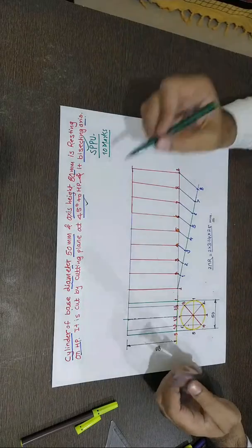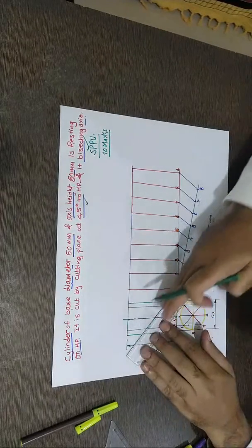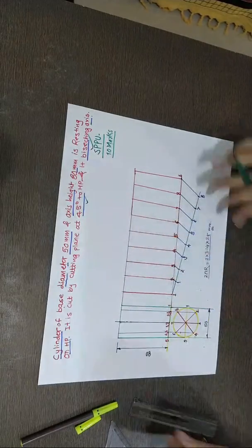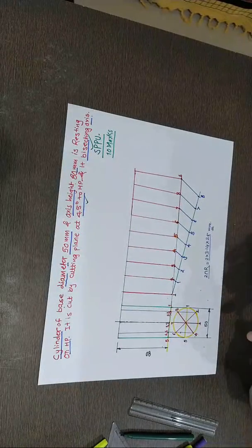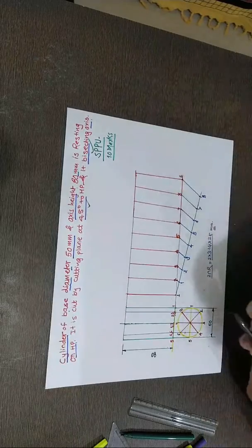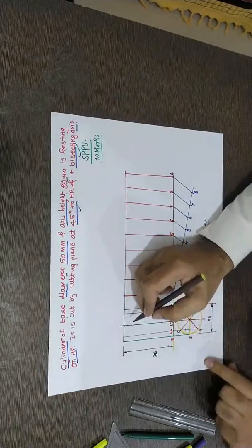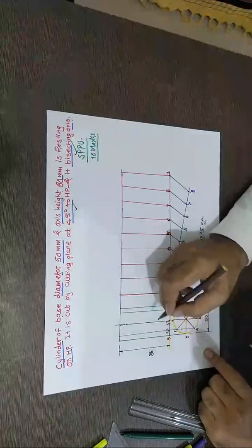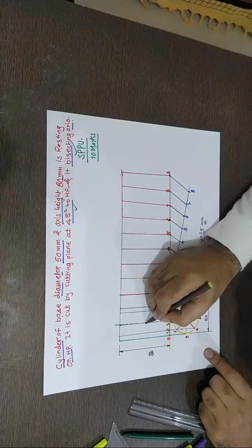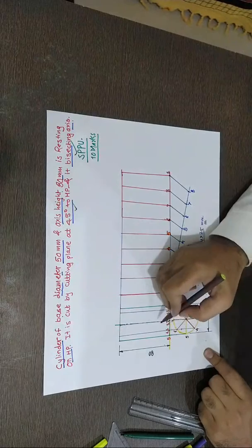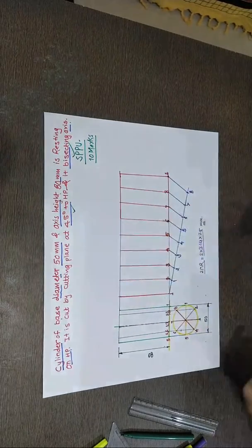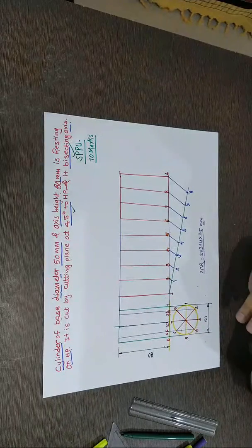Now 45. So you can take this angle 45 like this or like this, either or. So I'll take right now for this problem position like this. Again bisecting axis, instead of that they can give you the position of the plane is 20 mm from this, 100 or any other condition. Instead of midpoint of this axis they can give any position of a plane from the base, from the top face or any other intersection condition as well.